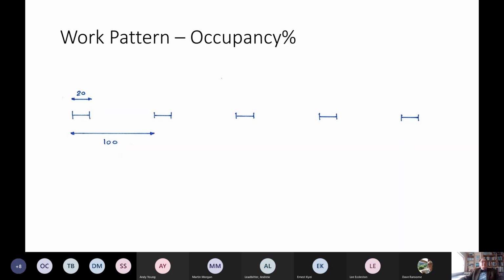You take the point that there's a notional periodicity to their attendance, and that in that continuing period, 20% of the time, somebody is exposed to the hazard. And so the simple answer is to put in a conditional modifier of 0.2 into your LOPA. But there are a number of traps for the unwary with this.